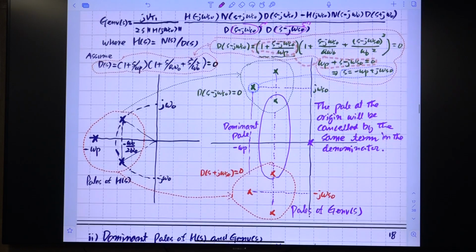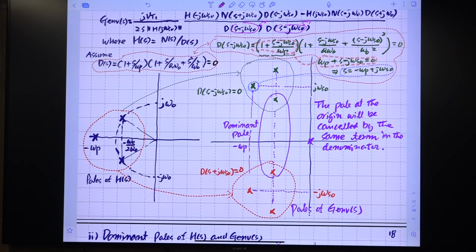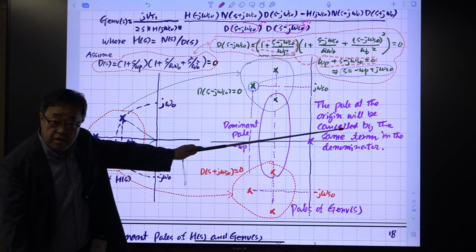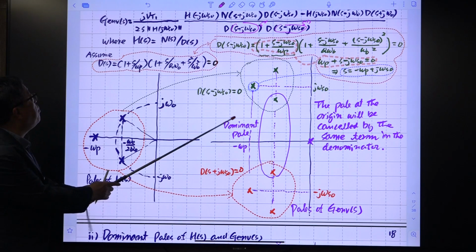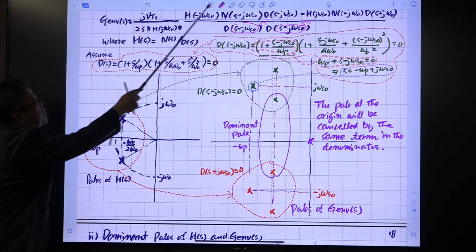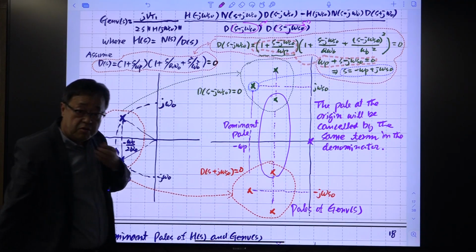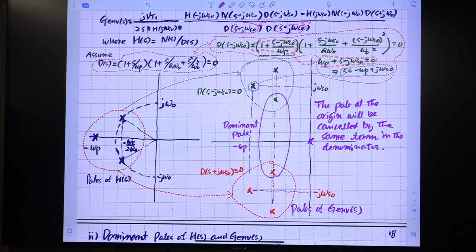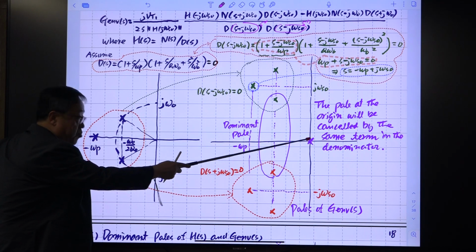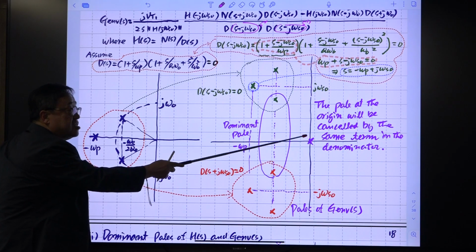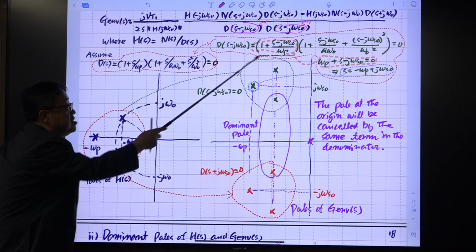That's good, right? One problem with this is there is an S here. This means there is a pole at the origin of this graph. You have a pole here. This is a big problem, right? But this pole will be cancelled if we perform this operation to evaluate the numerator. Another S term is always coming out, then that will be cancelled. So you don't have to worry about this. It will be cancelled eventually. So assume this does not exist here. Just consider we do this.